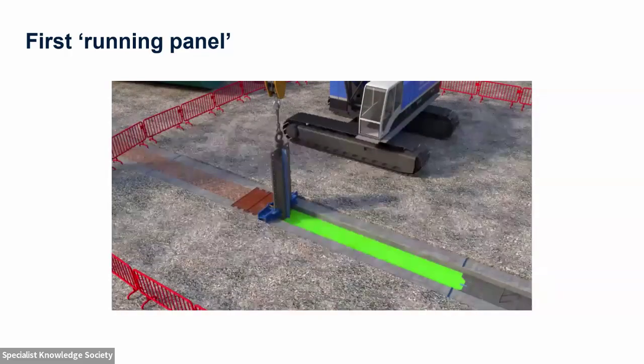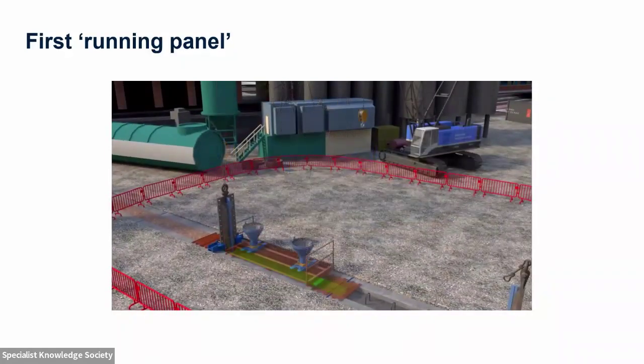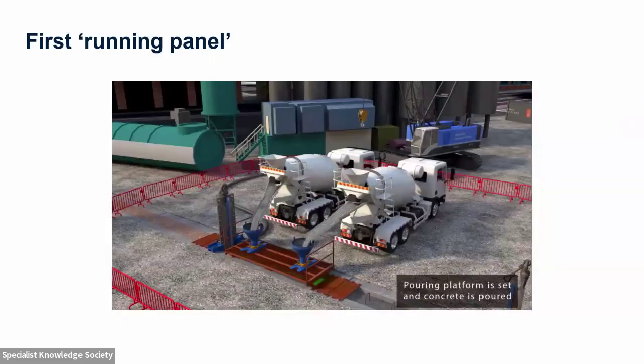construction. You don't really want to leave your stop ends in too long before constructing your next panel, because they start to get concreted in, and the longer you leave them in, the harder it is to get them out. So you have to try and plan your sequence of works around so that you've got a number of different areas you're working on, a number of different fronts, effectively, you're working a diaphragm wall from, so that you can complete your panel and remove your stop end